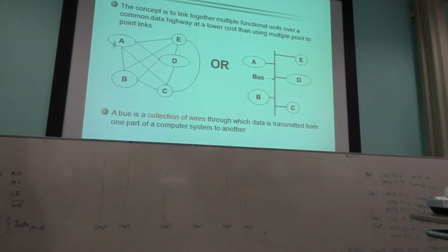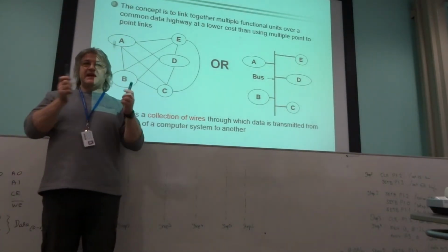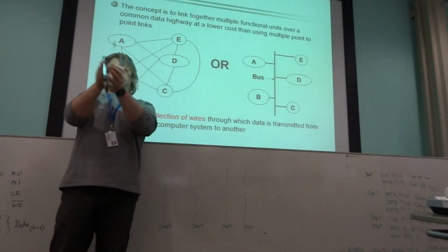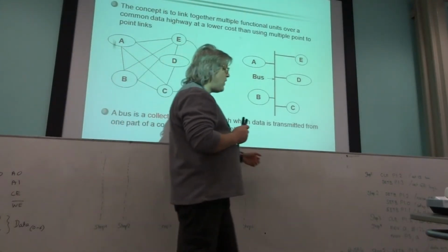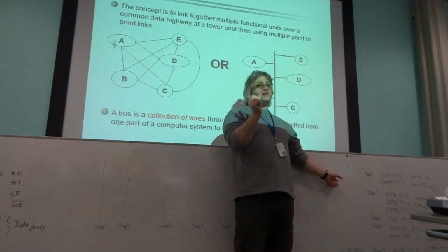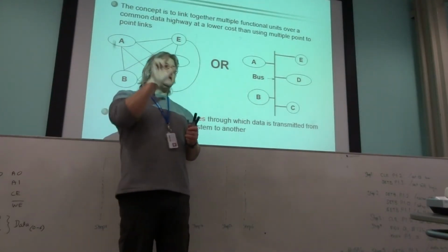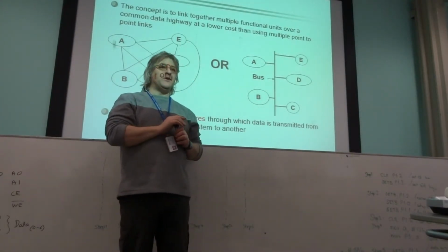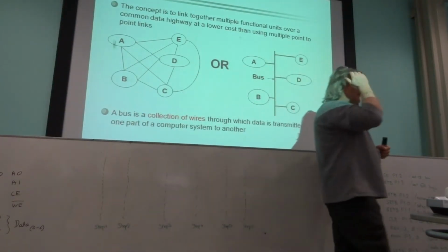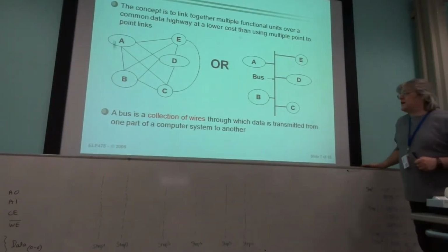Remember, it doesn't just give me the sequence, but associated with those timing diagrams in the real data sheet, you would also get information about setup and hold times. So we can see how quickly you're allowed to move between those steps. If you need to wait between steps, and sometimes you do, it might say you have to wait for 400 nanoseconds. What we would normally do there is insert a little delay loop in our assembly language to just do for however long, and then move on.